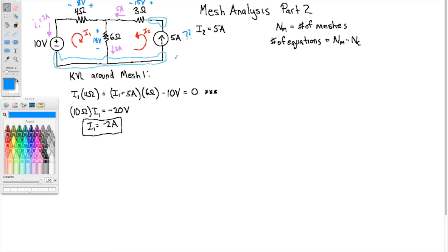Well, if we call this 0 volts down here, that's maybe our reference. Okay, well, we know that from here, this T node, to here was a drop of 18. So if this is what we're calling our reference to be 0, then that makes this 18. And then we know that there's an increase of 15 to get to over here.